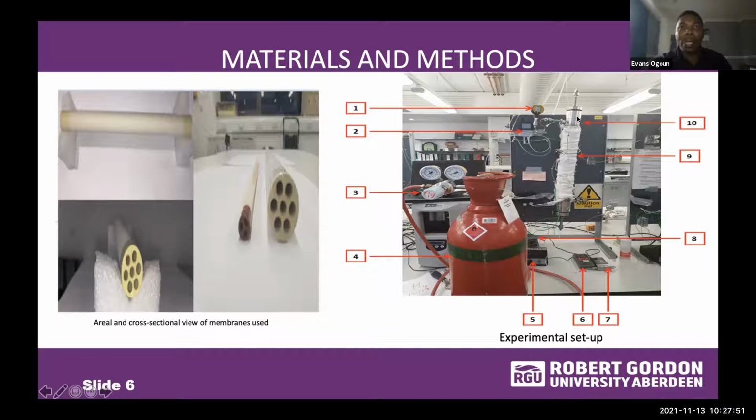The system is heated to a desired temperature and allowed to reach thermal stability. Natural gas is then released from the gas cylinder and allowed to flow through the nanoporous core to an exit line where the gas is discharged. The pressure gauge is monitored and regulated to a desired pressure and temperature condition, after which the system is allowed to operate for a period of time for the reading on the flow meter to stabilize. Once stability is attained, the readings on the flow meter are recorded.